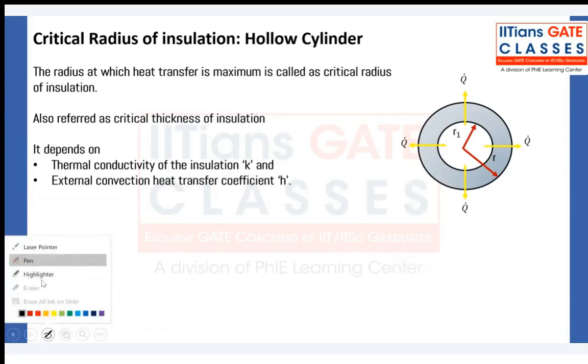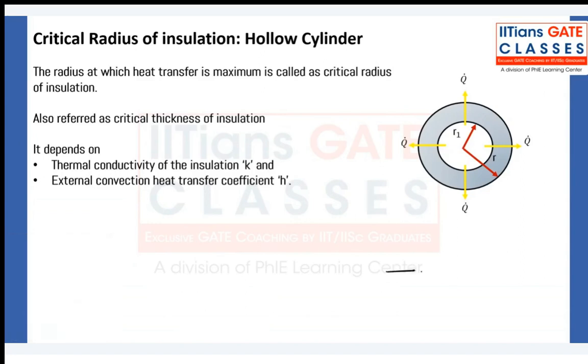So, for example, you have a wire and current is flowing. Because of current, there will be resistance. Because of resistance, there will be heat generated. So, the temperature of the wire is going to increase. As the temperature increases, there will be more resistance and more loss of power. Whatever heat is generated, you cannot do anything about it. If you are passing current, then heat will be generated because resistance will be there. But what can you do? You can conduct that heat out. So we insulate this with insulation.